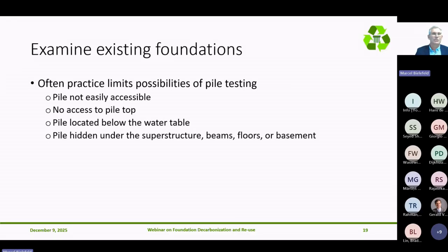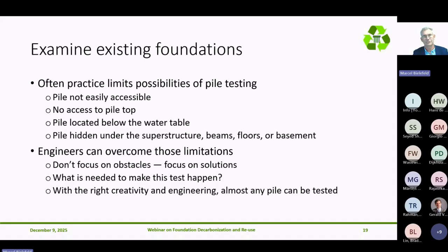And it's often not done because it is also not often so simple. The practice limits quite often the possibilities of pile load testing because the pile is difficult to access. It's always underneath a superstructure because that's what the foundation is for. But it becomes even more complicated with groundwater, with the soil, basements and things like that, which makes it hard to access the pile top to test.